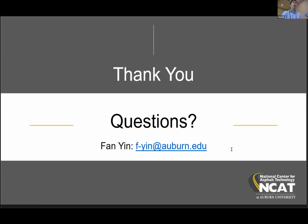Yeah, I mean, that's a good question. We did not look into that option. I know that is considered one of the practices out there, using softer binder to accommodate a higher RAP content. But for this study, the scope is to focus on different ways of adding rejuvenator. To be honest, I think balanced mix design provides the opportunity for the contractors to engineer, to innovate, whether or not using softer binder or using rejuvenator, they need to consider the economics, the performance, and the environmental. So I say both approaches could work, which one to decide is really a mix design question, but we did not look into that in this study, but we have some other study where we look into the softer binder.